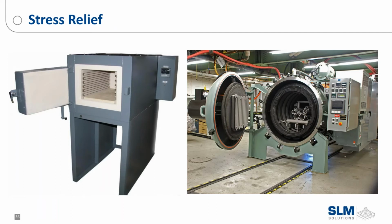So the first step, quality verification. X-ray computed tomography, or micro CT: what we're doing here is looking at voids inside of the part, without cutting the part open and without having to create density samples. We can take this part, scan it, and see all the voids inside this piece. In this top picture on the left-hand side, all those little triangles and blue and green and red dots are voids inside of an additively produced part.